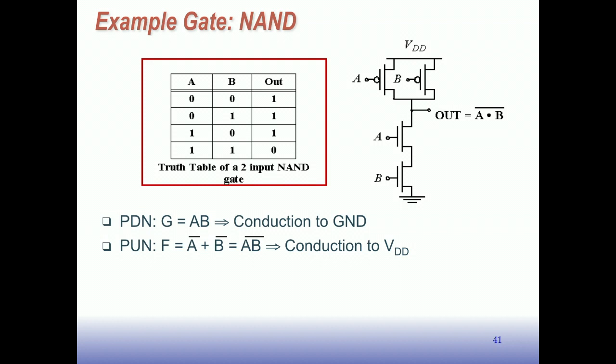So we generate a 0 if this function is true. Right. And then the pull-up network is this. Since the symbol reminds you that for P-type transistors, it's effectively inverting the signal that connects to its gate, this is A bar or B bar, which through De Morgan's theorem says A times B, bar.